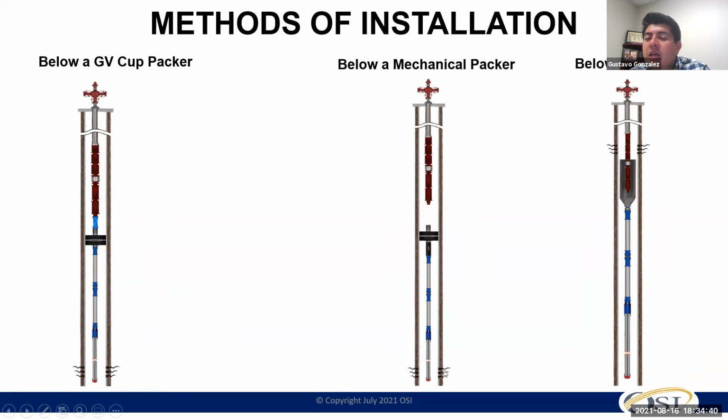In case you're still keeping your perforations underneath it, and either you have a lot of issues with those cup packers because they're wearing off, or you are putting too much weight below your ESP and you want to avoid any risk of pulling your ESP to one side and facing too many broken shafts, the other approach you can use is to go back and set a mechanical packer or rotational packer, with your sand control system underneath it, similar to the previous one,